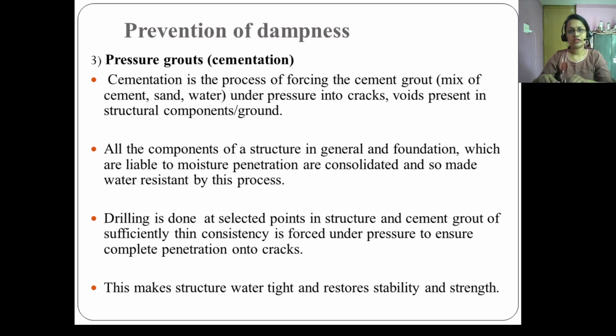Next is pressure grouting. Cementation is a process of forcing cement grout, a mix of cement, sand and water, under pressure into the cracks and voids present in the structural components and ground.